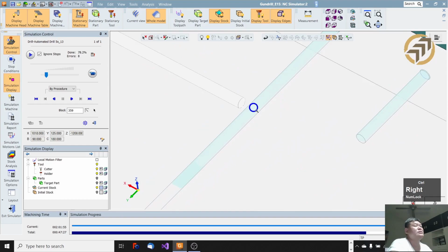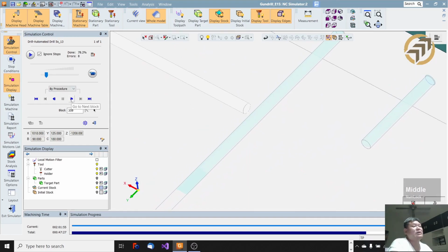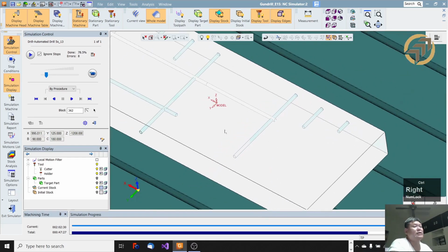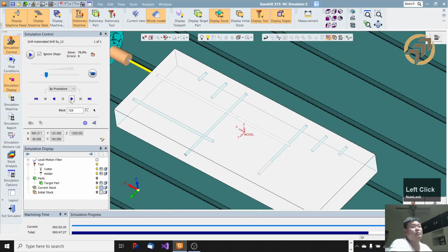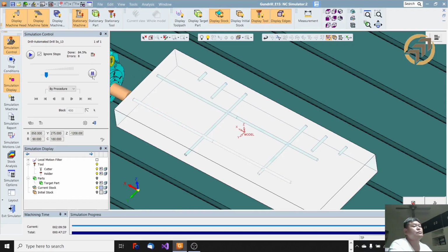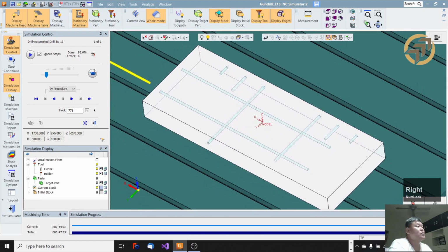Then you change the feed rate to 50% and then through the hole until 5 mm after the hole, and then to the end with full depth. Right. Same also for this hole.